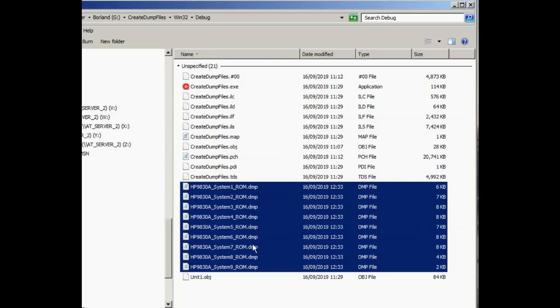I'll reprocess this data in the same way that I processed the data from the emulator in the first place, and make sure that the reverse process results in the data I started with, just to make sure that I haven't introduced a bug along the way somewhere. But it is looking very like it's just a faulty ROM or two within the ROM card.